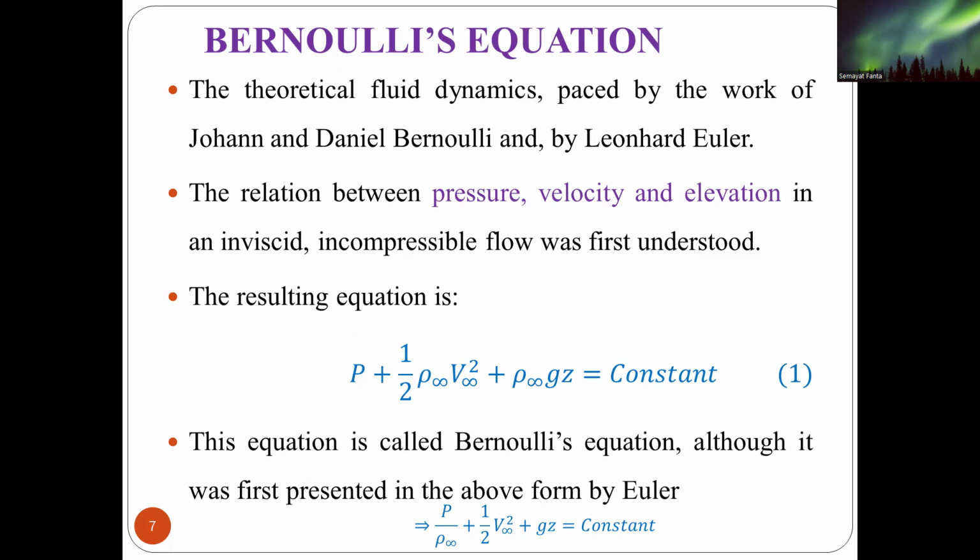And we demonstrate this Bernoulli equation using the Venturi tube apparatus. On that, we can find different cross-sectional geometry or area difference. In some cases, if the Venturi apparatus is inclined, an elevation difference may appear. But in most cases, we consider the elevation to be constant.